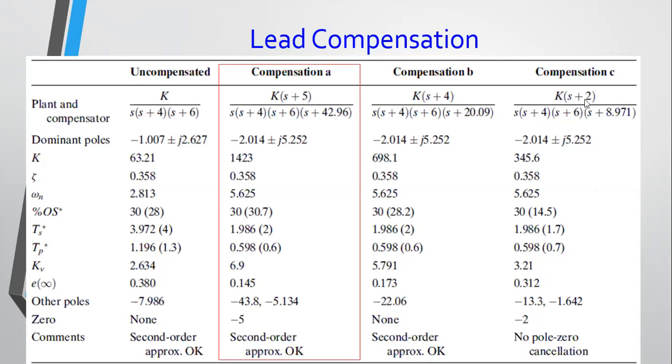Now, in this case, we are introducing your 0 at -2. So this is still your operating point, and you find your settling time is more or less very similar, but in simulation it is actually lower. And your peak time has also reduced. And then for the steady state error, before it was 0.308, and now it's 0.312. So steady state error has reduced to a lesser extent when you do that, but overall it's fine.